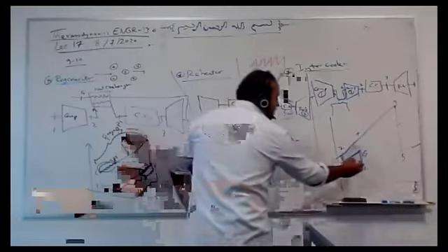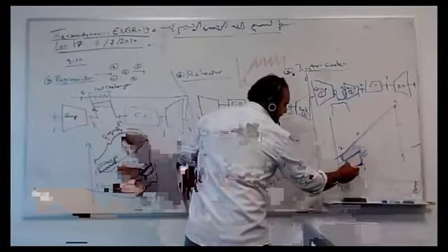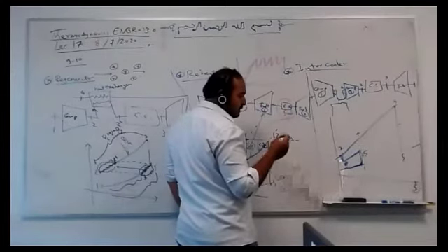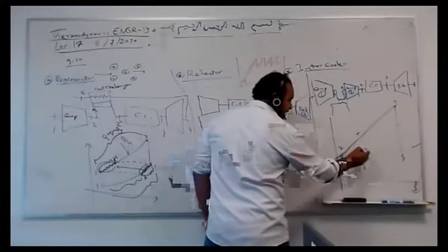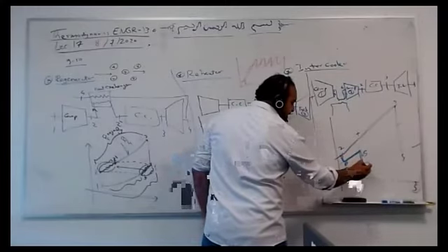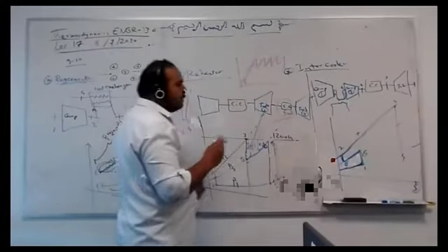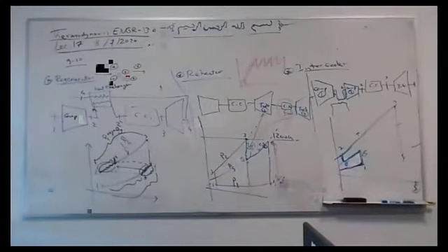Why did I not cool down from here directly? Sometimes if you cool it directly, it may freeze, become solid. But when you compress and cool, this temperature is greater than this, so it's not freezing yet. So you can compress. Sometimes you need it in liquid phase. Here it is not a big deal, but for Rankine it will be a big deal.